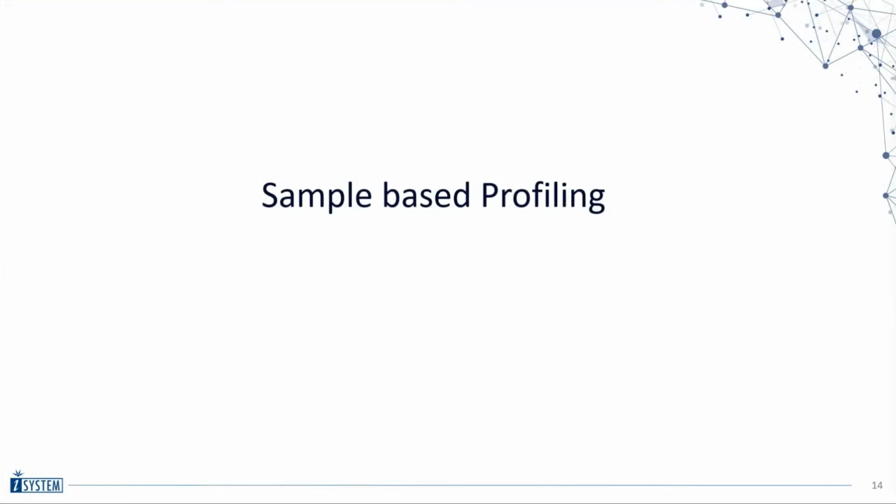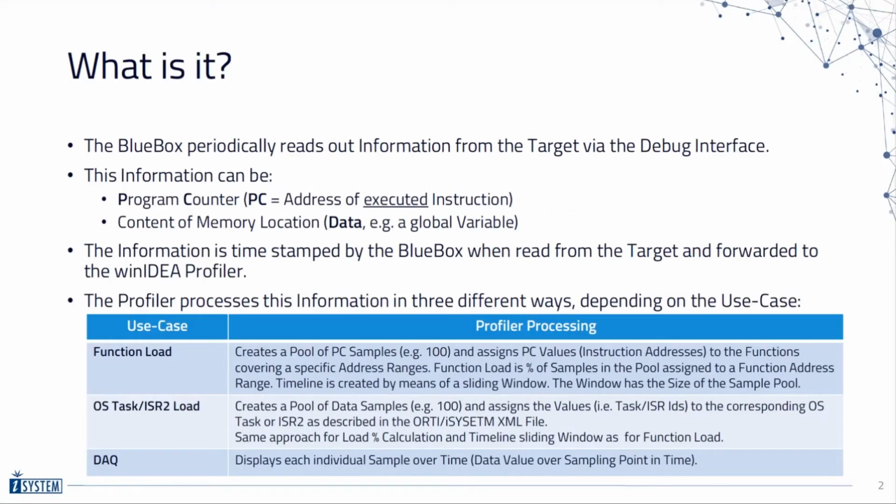Now let's take a look at the new sample-based profiling feature. Anyone who has ever used a trace interface knows the power and control it provides over software development and especially timing analysis. If you have the ability to set up one or more of your development systems with an emulation device or a special mock-up to get trace, we will always recommend doing so. But sometimes a trace interface is not possible. In those cases, the sample-based profiling can be very helpful.